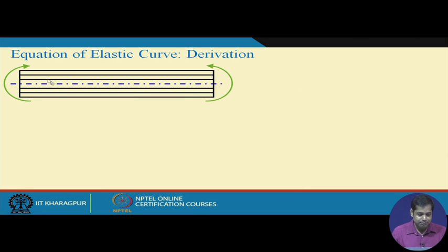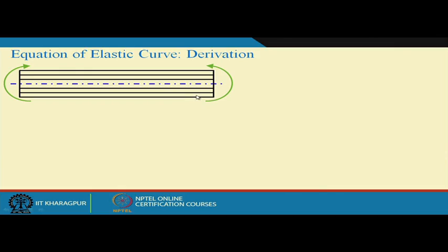Now consider this is a beam which is subjected to pure bending. I mean there is no shear force, only bending moment. This is the neutral axis, the blue line that you can see. And in this portion we take some lines. You assume these beams are essentially a collection of certain fibers across the depth. So we take some fibers above the neutral axis, and some fibers below the neutral axis. And the fibers or the planes are in this direction along the length of the beam.